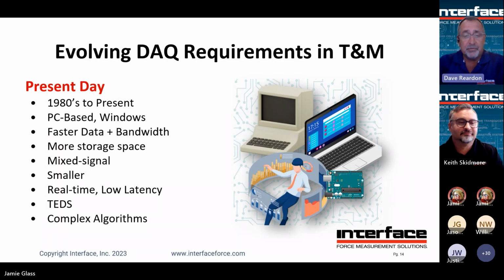In addition to that, we started using a lot of mixed signal data acquisition systems. Systems started to get very small. Real time, instant gratification, is what we were looking for here, and we were able to make it happen. In the last 20 years or so, they came out with a system that makes it a lot easier to program your system by using TEDS chips. This stores information about a given sensor on a chip that is either within the connector or even on the sensor itself, so that it identifies and programs the system as soon as you connect it up and start recording data.